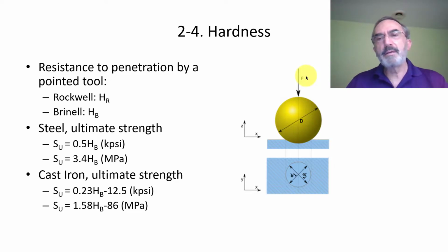The test is cheap. The test is non-destructive. That means I can go to a bridge and put a portable indentation machine on one of the steel beams, push against it like this, leave this indentation, measure it, and go away. The Department of Highway never knows I did it. Nothing's going to happen to the bridge. No one knows that I put this little indentation there. In fact, there is micro indentation and nano indentation, so you can leave a mark that you cannot even see with your eyes.